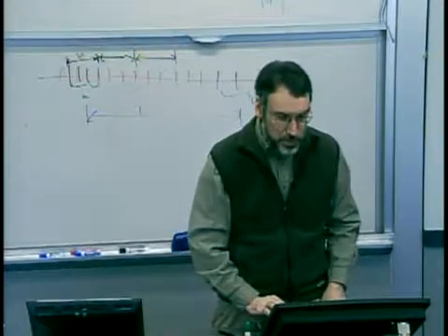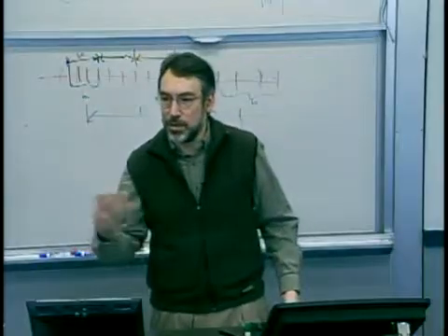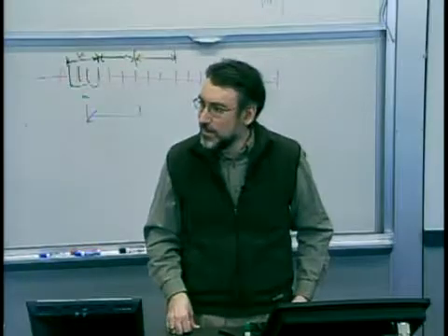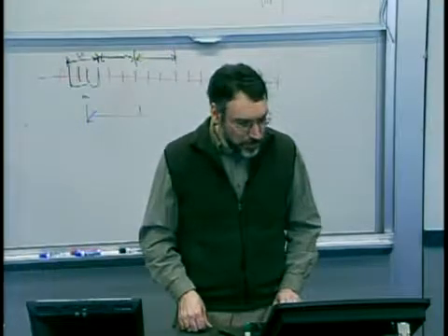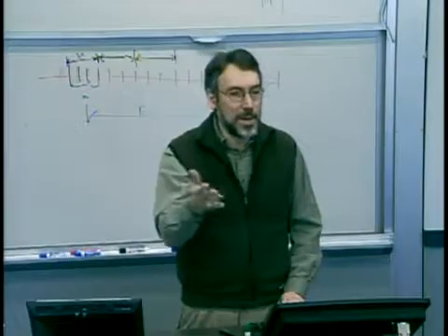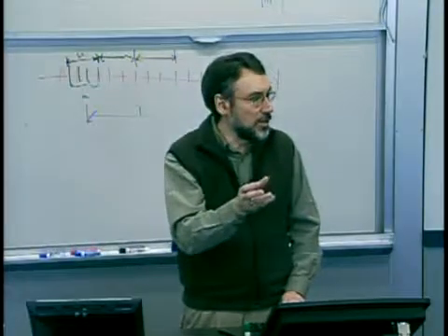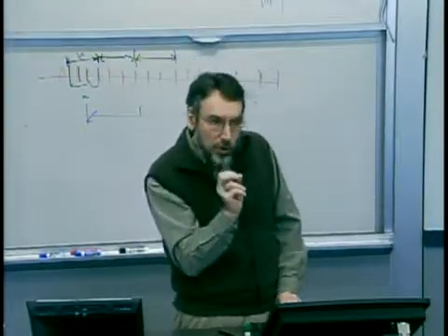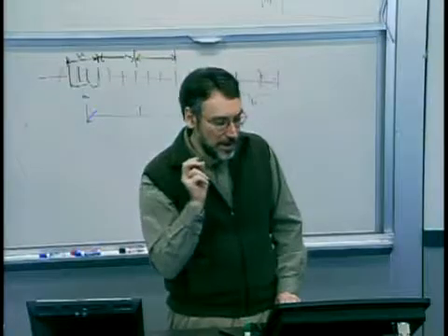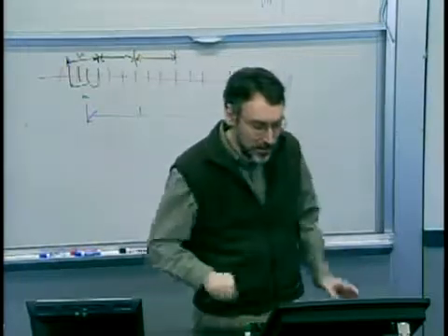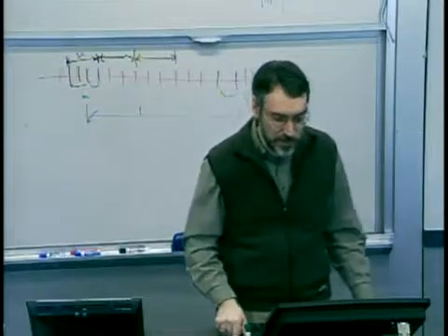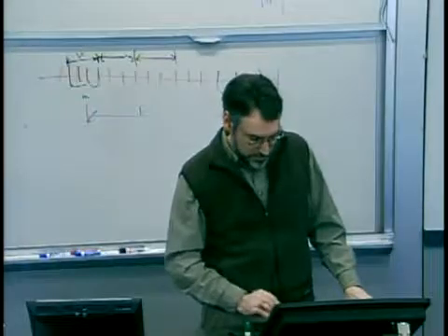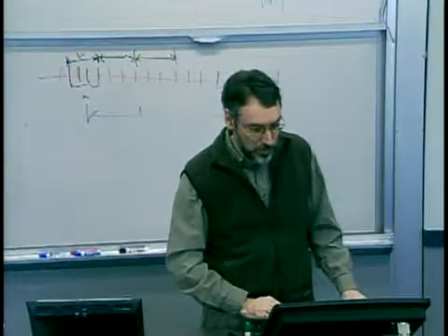Okay. So why do you want something like a CP of 2 or a CPK of 2? Because 1 part per billion seems awfully small, right? And the reason really is so that you are robust to small mean shifts, so that even if you've got that small mistargeting, you've still got enough room in an inherent process width, say, a CP of 2 or CPK of 2, to be able to have a very small number of non-conforming parts.